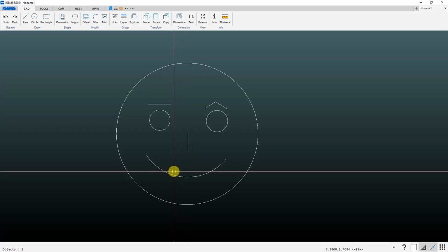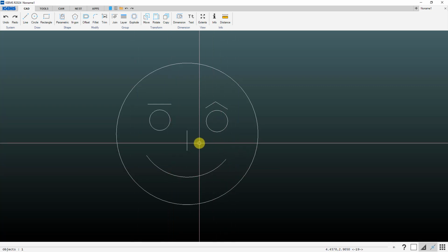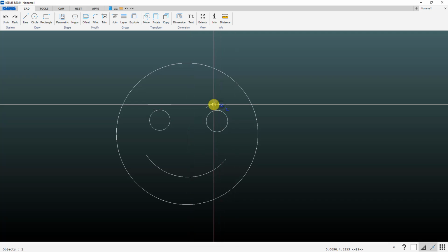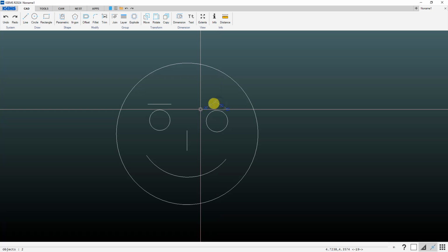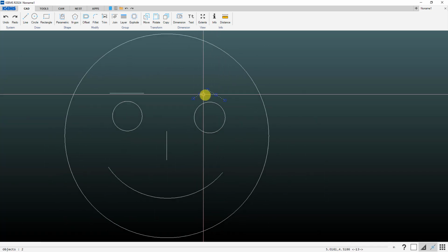Anything that's not connected, like the circles here, would be considered an open contour. And if we want to cut those, we have to tell IGEMS when we're creating our part that we actually want to cut those, because normally things like dimension lines, it assumes that you don't want to cut. And if you have something like this where I've drawn this and this is right now two separate lines, you'll get a little bit better result if you join those together as one polyline.